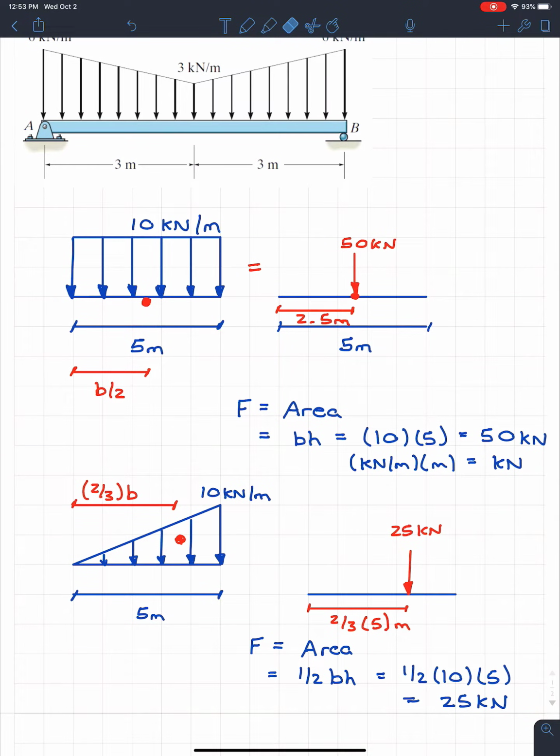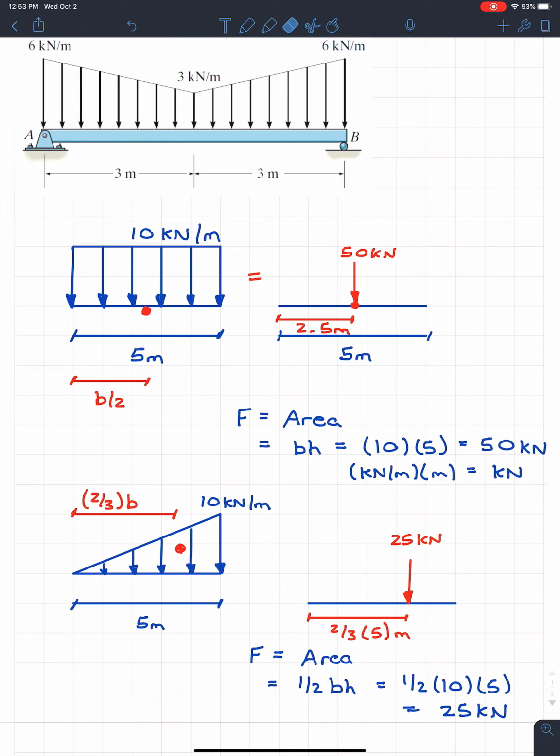Case 1, the rectangular load, well, that's what we do for buildings. We say that the people will have a nice uniform distributed load, something like that. We assume the worst case scenario, so we say that it's everywhere. The second case, a triangle, that'd be a good representation of snow load. As you guys know, if there's kind of a bank or something, the snow piles up in the corners. Well, that's what the snow would do. So these are the only two cases you really have to know, but let's try and apply them to this example.